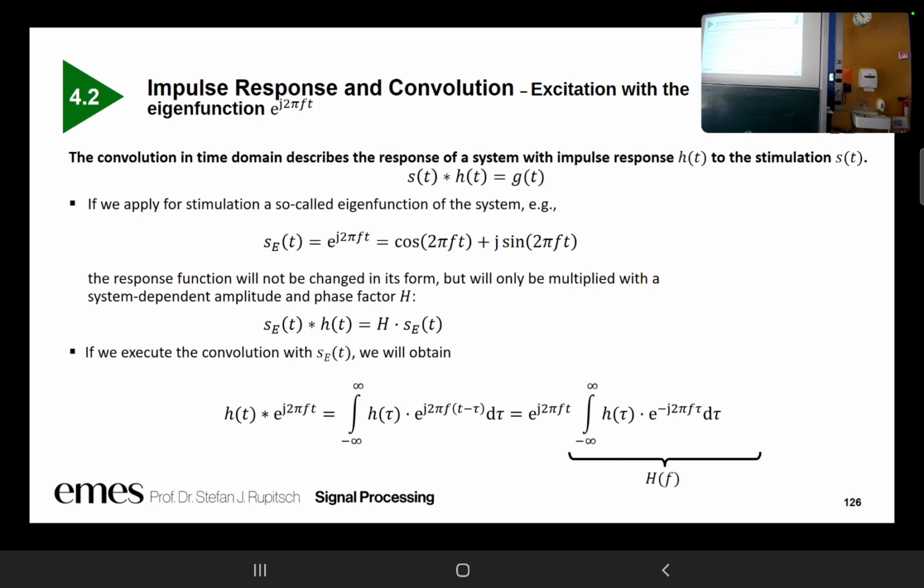The spectrum analyzer works exactly by exploiting this. When you have the local oscillator, the oscillator provides your circuit with a frequency, and it takes a look at the output. It depends on the spectrum analyzer. There are several spectrum analyzers able to perform nonlinear analysis. That means they also take a look at the higher order components.